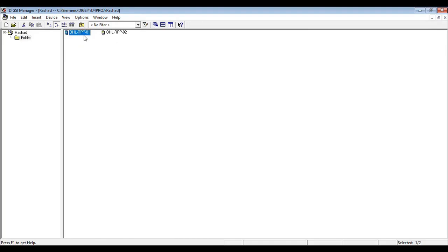From the relay protection between the first and the second file, let's think together. In the previous videos, when we were theoretically discussing the CID file, we said that we have three steps to easily define the CID file. The first step is identifying the logical nodes. And we mentioned that logical nodes are divided into two types: standardized logical nodes and generic logical nodes.